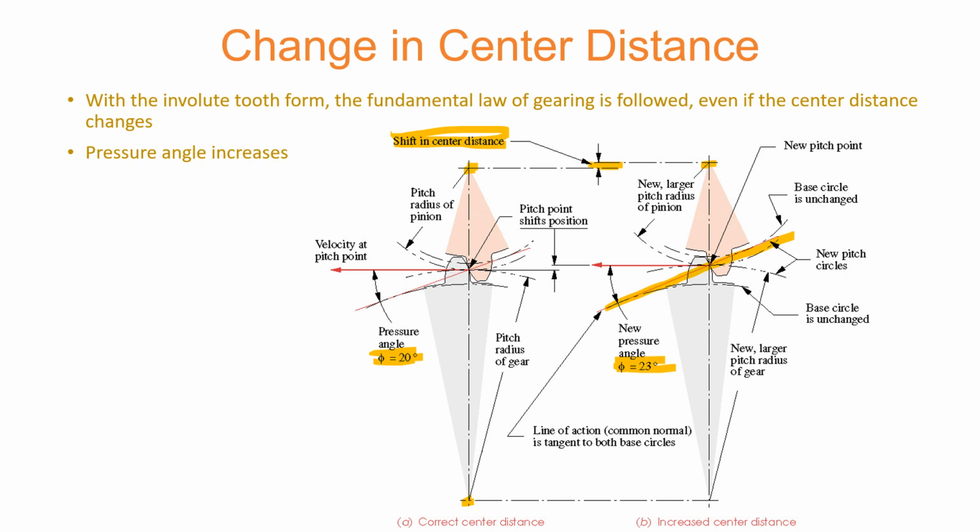When the pressure angle is a bit larger, it means that the transmission of forces is going to be carried out in a somewhat different fashion. Whether it is advisable or not is generally the challenge in front of the design engineers, and the standards illustrate quite a few sets of rules in order to allow someone to choose the appropriate pressure angles.